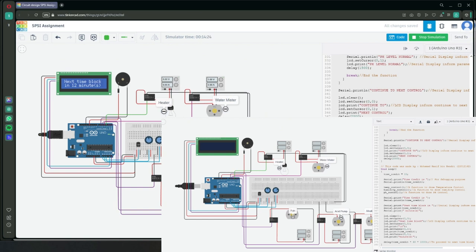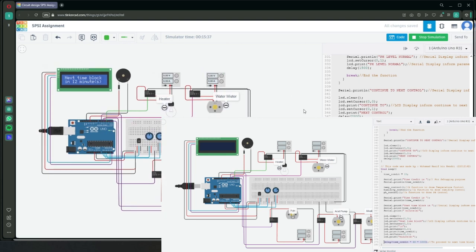In the coding, it is written as this line here. So, it will delay for however much time credit is left, and the calculation is time credit times 60 times 1000 in order to convert minutes to milliseconds. Once the idle time is over, void loop will repeat, thus starting a new loop. This will go on until the aquaponic system is closed.